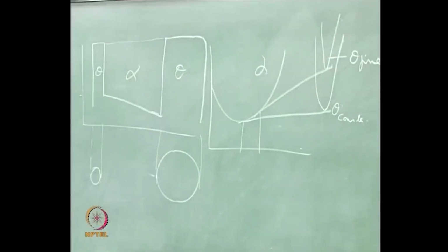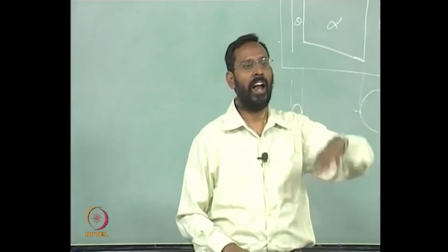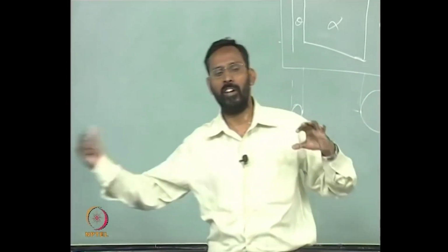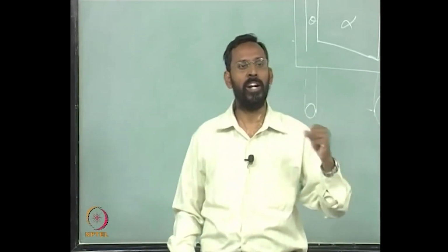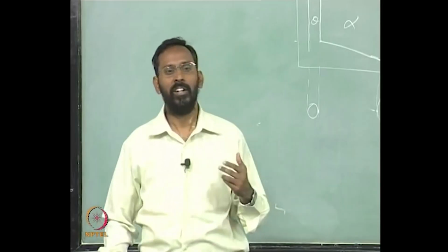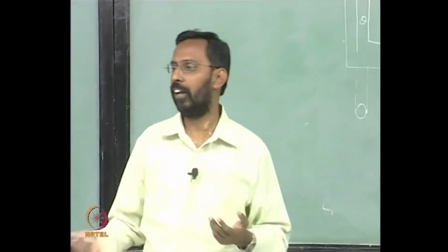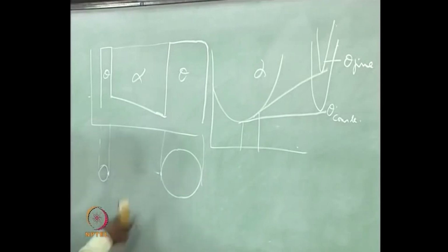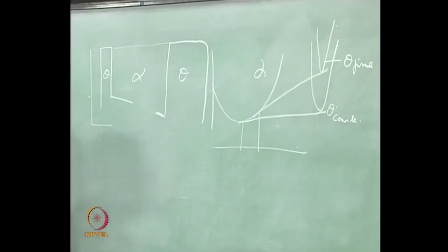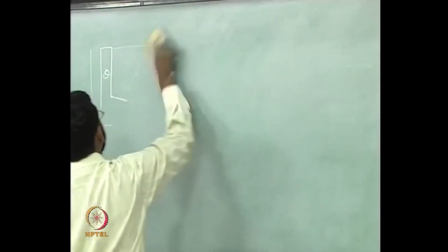But if you consider a case where you have different levels of heterogeneous nucleating sites available with different hierarchy, and somewhere the nucleation takes place first and somewhere else a little later, during this process the one which has already nucleated starts growing. As a result you would see differences in the sizes, and once there are differences of sizes, you will definitely see Ostwald ripening take place.